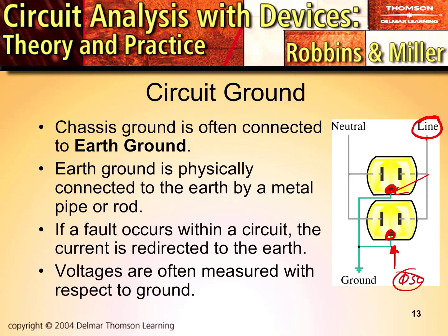So the whole idea of the safety ground is what protects you from getting shocked, because it shunts any of that dangerous current to safety ground, which has its way back to the power system ground connection that's common for all of the grid, and overload protection trips, and you're safe from any issues.